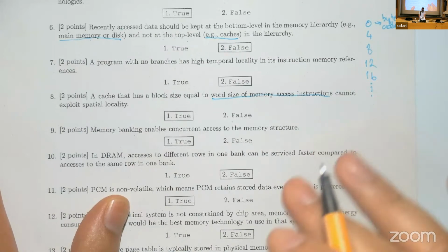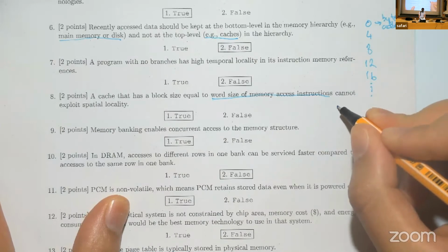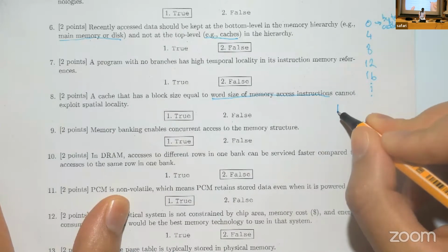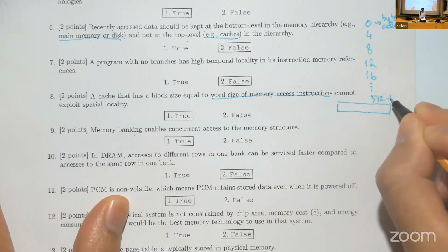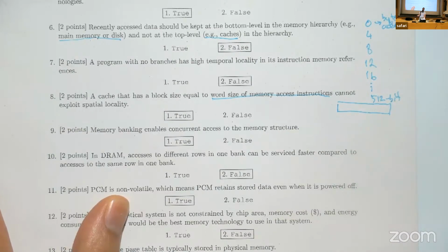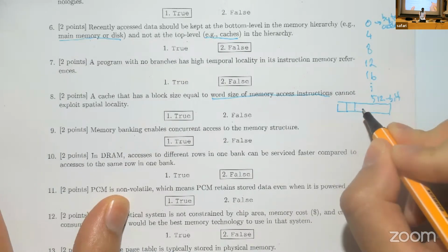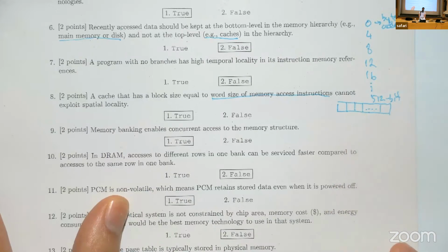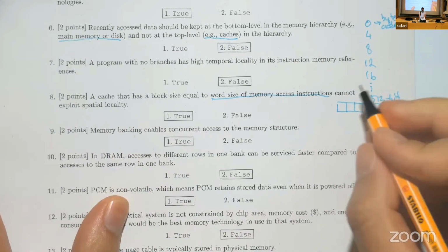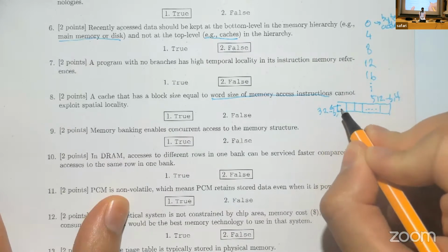Yes, so let's look at what we have today typically. You have a cache line size of, let's say, 512 bits, and let's say your word size is 32 bits. This means you can fit 16 of those words in this cache line. Why this is important is you will access this word from your processor.